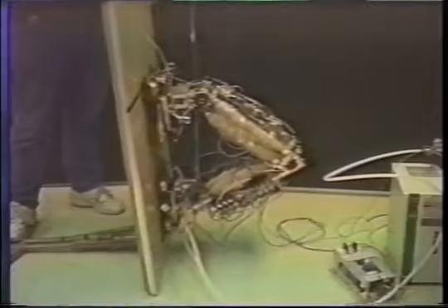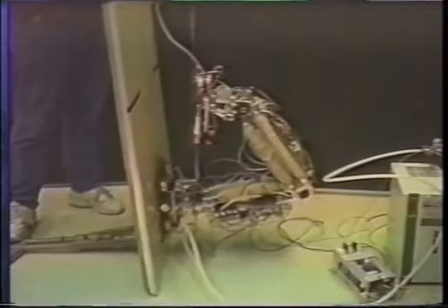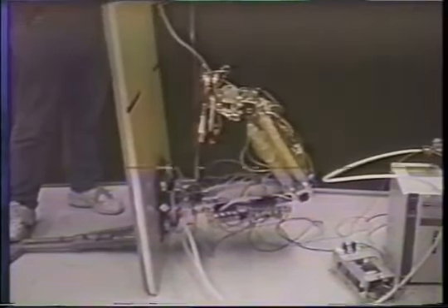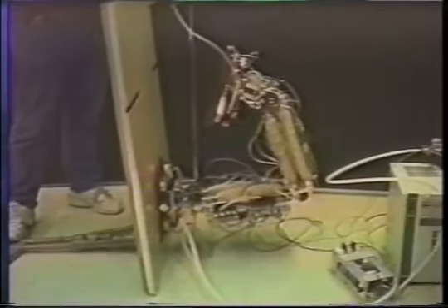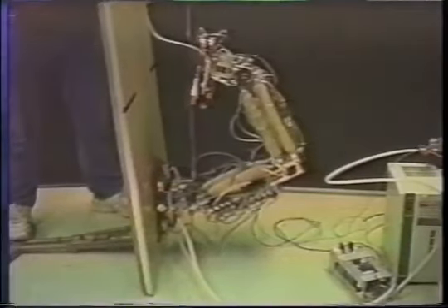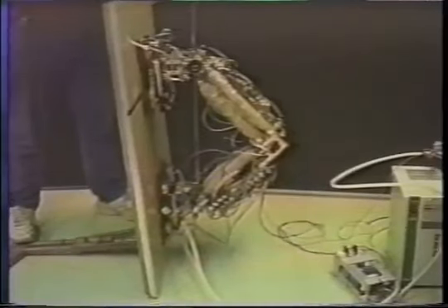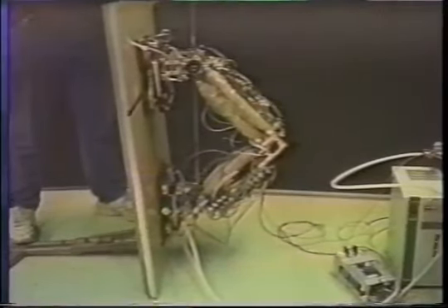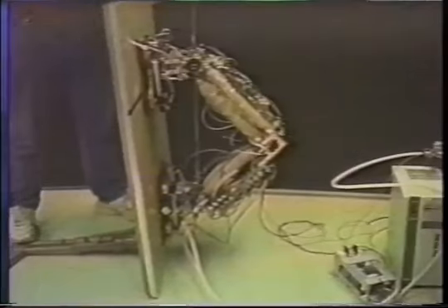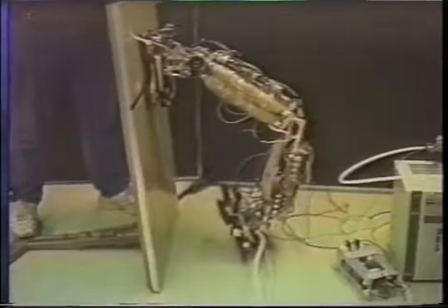Finally, we will show one of our first tests with Robin climbing a vertical surface. Here you can see the flexibility in the spring-like actuators, as evidenced in the oscillations of robot motion. The lightweight valves used by Robin have very low control bandwidth, and it is difficult to damp out oscillations with this control system.